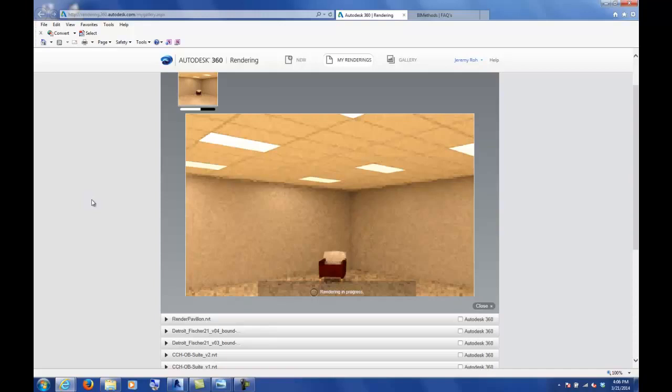What that means is if you render from not your computer, but from one of these computers, some of your materials, when it goes to the cloud, might be scaled wrong. For instance, stone pavers are going to show up like boulders when they go to the cloud. They scale up by 12. I've had all these people send me renderings, especially in my class, where I'm like, wow, that scale is just way off, and they've tried to tweak the material, try to change it, and it keeps coming up at that size. Service Pack 1 apparently fixed that problem. Because when I render on my computer, I never have that problem, and I have all the service packs.